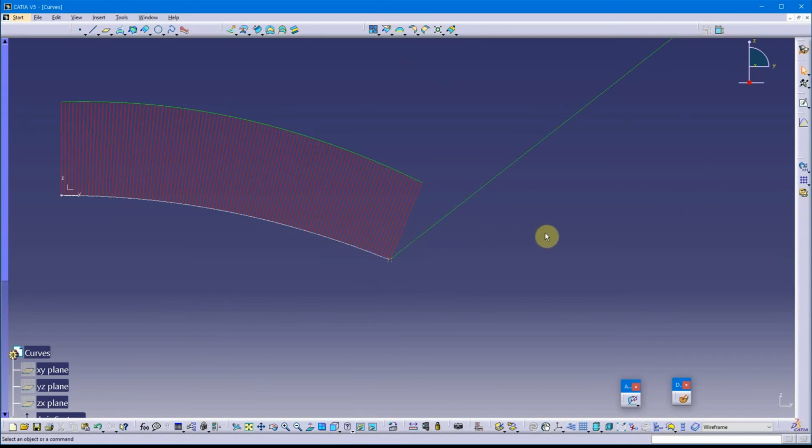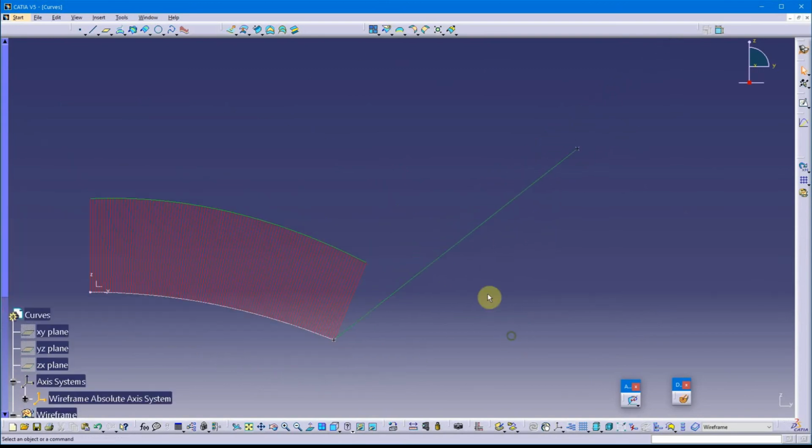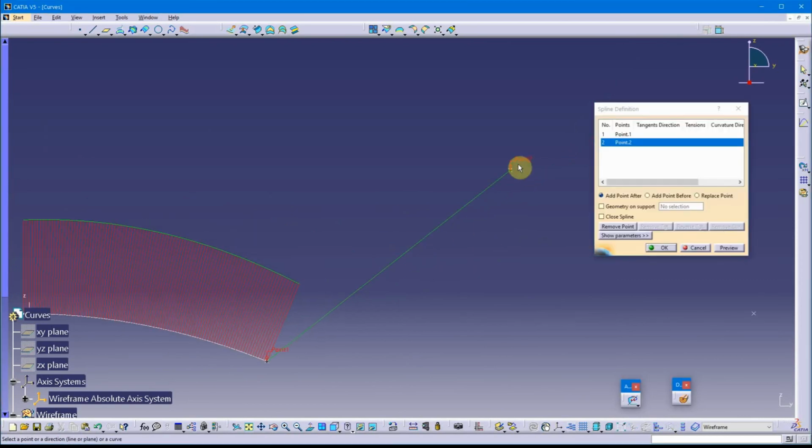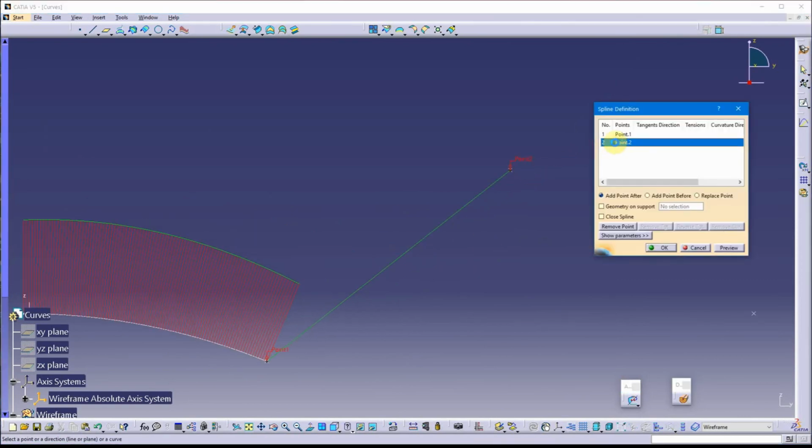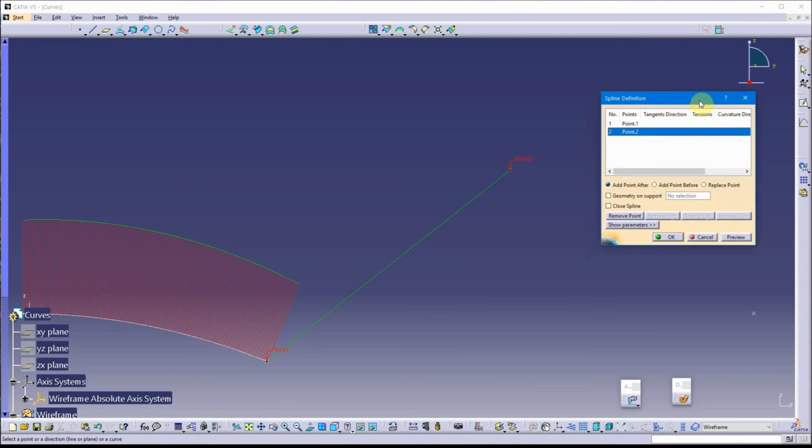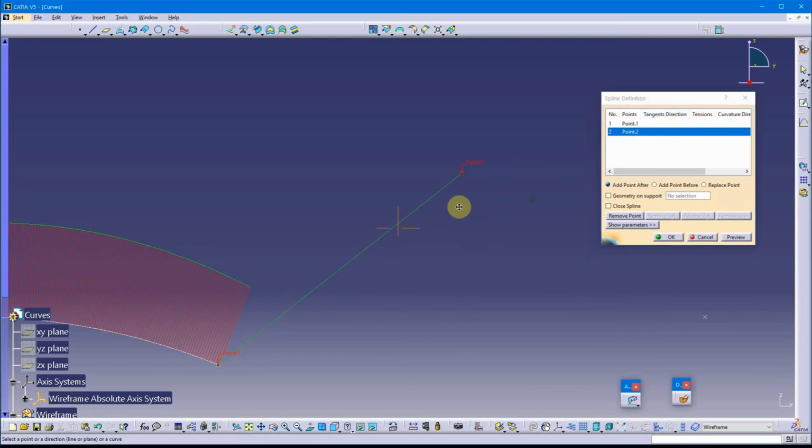Now, I'm going to jump up here to this curve and just do some play, if you will. I'm going to go to point 2 of this curve, and let's throw in an explicit continuity to the y-axis. So that will take this point, and the y-axis is going this direction, so it will make this curve come tangent, so the curve will flow around this way eventually.